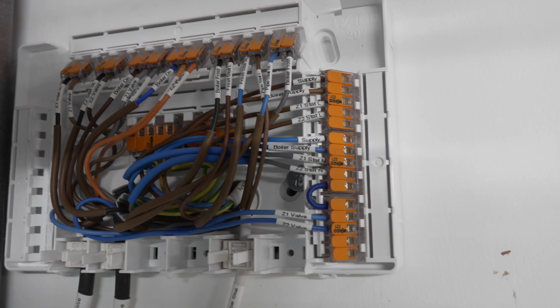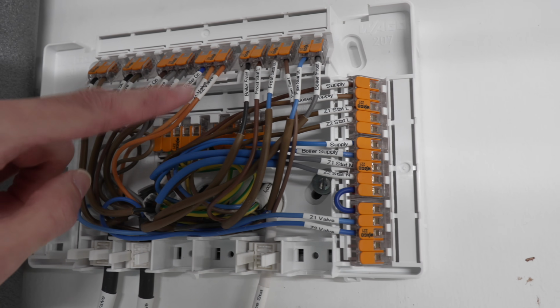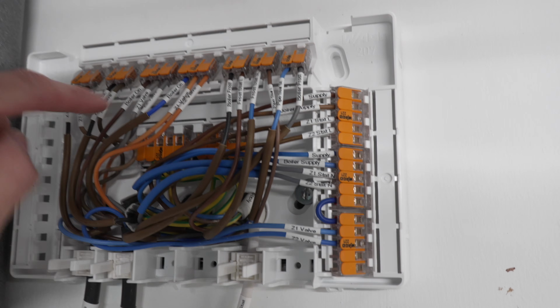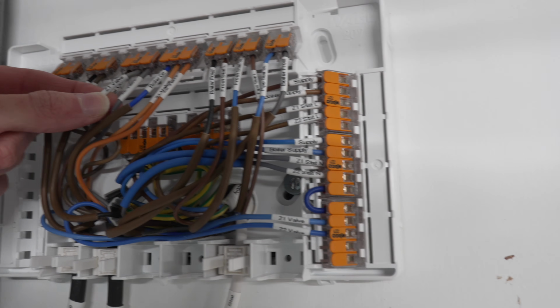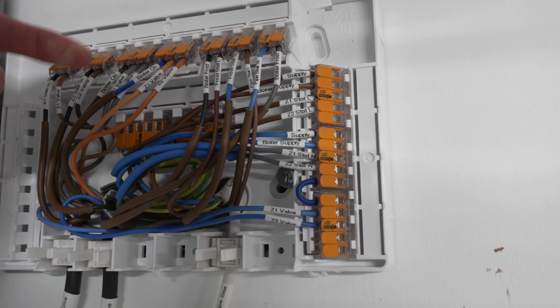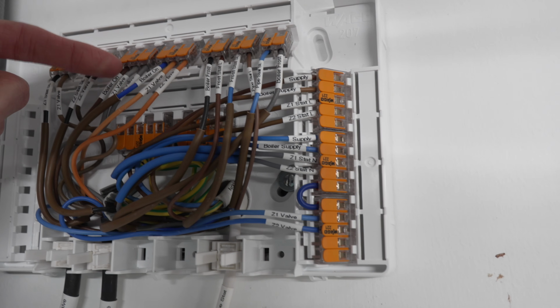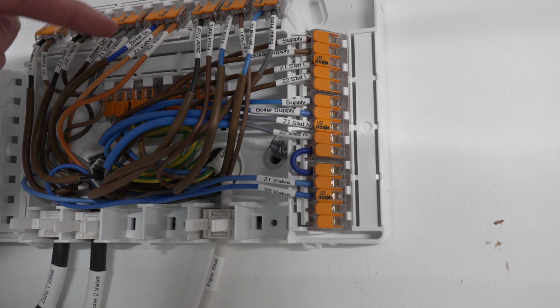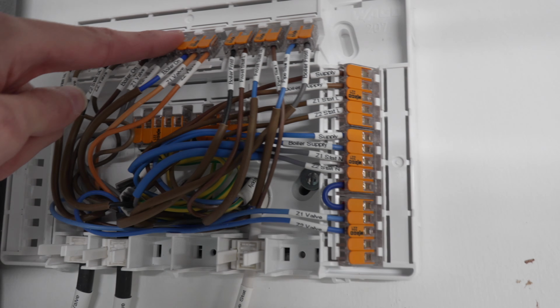And if you remember what I said before, when the valve fully opens up, the grey wire and the orange wire get connected together by a switch inside the valve. So what this means is, say for example the zone 1 valve, when that turns on, the grey wire of the zone 1 valve connects to the orange wire of the zone 1 valve. That way the boiler on signal will get switched via the valve back up here. These two boiler on signals get connected together via the valve and it turns the boiler on.